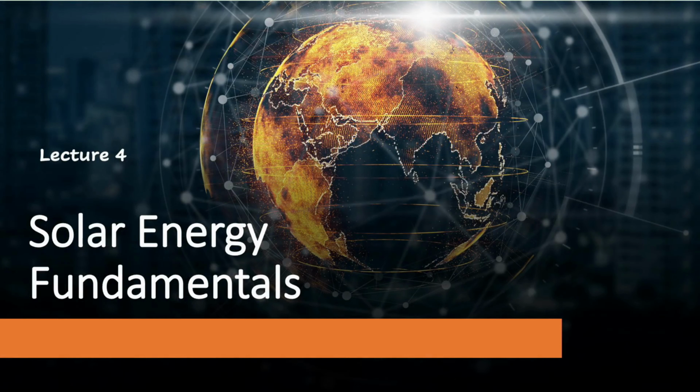The answer to your query is that all solar devices, whether a solar panel, solar flat plate collector, solar concentrator or any other solar device, are installed on the earth surface, instead of on the equatorial plane. Since the earth is spherical in shape, the devices lying on the earth surface can never be parallel to the equatorial plane, and hence the sun's radiation received by the surface will be at a different angular position than for an object placed parallel to the equatorial plane. So, for precise evaluation of the performance of solar devices, knowledge of these angles is a primary requirement.